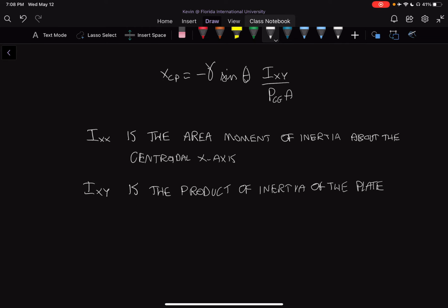And it makes it a little bit easier because we can get rid of some terms in the equation by using gauge pressure. So in most cases, the ambient pressure is neglected because it usually acts on both sides of the plate. So for example, if the plate was, let's say, a ship vessel or something like that, then one side of the ship vessel would have ambient pressure on it and the other side would have water. So the atmospheric pressure would actually cancel out. So sometimes we like to use gauge pressure for these types of problems because it simplifies our equations.